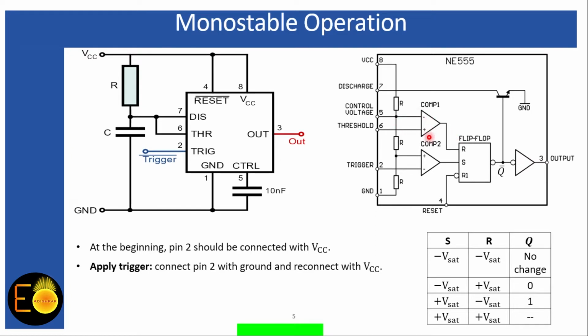So here, 2 operational amplifiers are used where we can't see any feedback resistance from the output to the inverting terminal. So that means these 2 operational amplifiers are being used as comparators. This is comparator 1 and this one is comparator 2. In some books, you may find this one denoted as the upper comparator and this one as the lower comparator. In my tutorial, I will use comparator 1 as the upper comparator and comparator 2 as the lower comparator. Simultaneously, I will use these names.